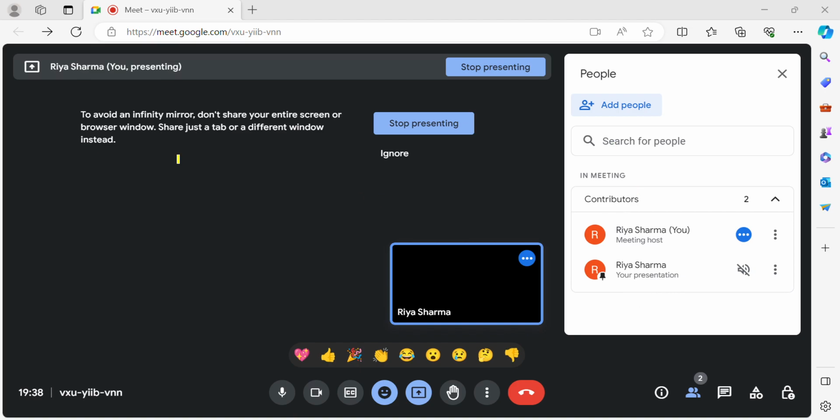If the exit temperature of the hot air is 20 degrees Celsius, what is the exit temperature of the cold water in degrees Celsius? So here the Q loss has come into the picture, so let's see how we will solve it. With the similar concept I have told you, when there is no mass exchange, we go by Q in minus Q out equals Q loss. So we just have to equate m Cp delta T of air to m Cp delta T of water plus the Q loss. Here m dot of air is 3 kg per second.